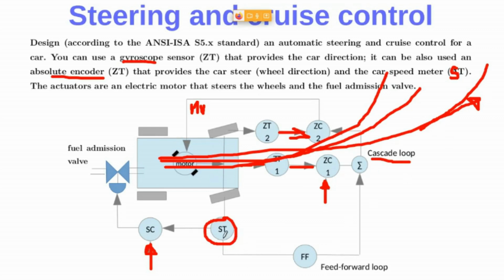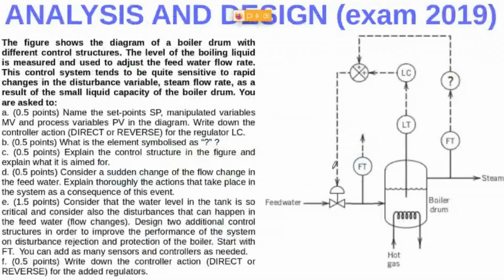So that's why, depending on the measurement, I propose to apply a feed-forward control strategy in order to control the car direction in advance, to apply an additional manipulated variable for that car direction. So it is added to the primary loop, that is the car direction control.